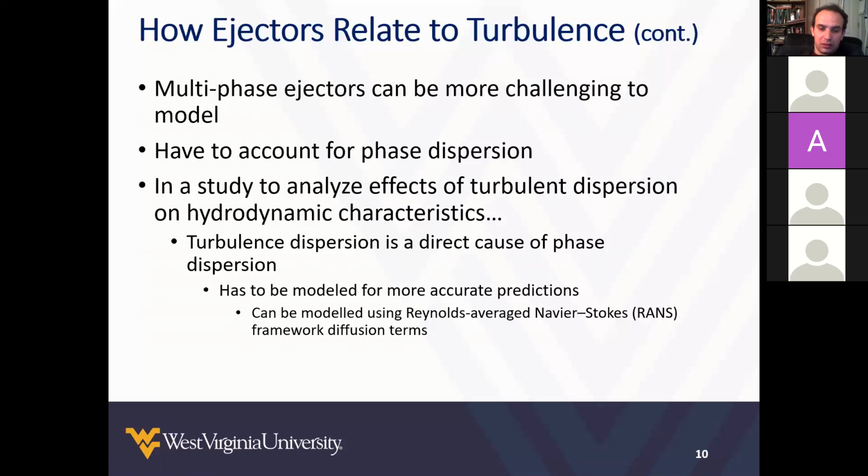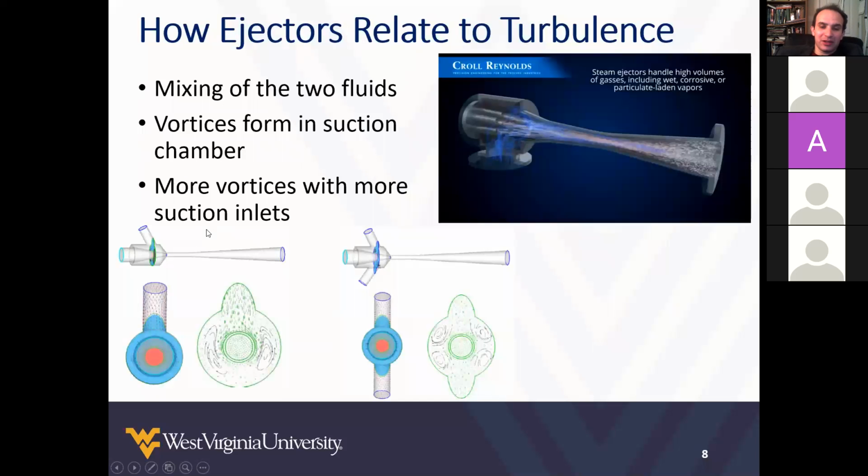I think the velocity coming out of the nozzle for our specific ejector was around 30 meters per second. And that was, I think, about a half a millimeter or 1 millimeter outlet diameter. So that's what I asked. It looks quite small, like a small pipe, but still because of very high velocity, it becomes turbulent, and even stronger, right, turbulent.